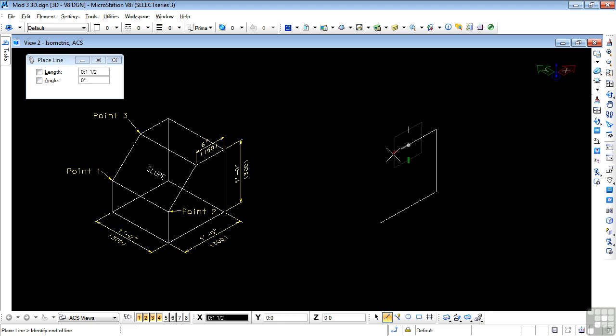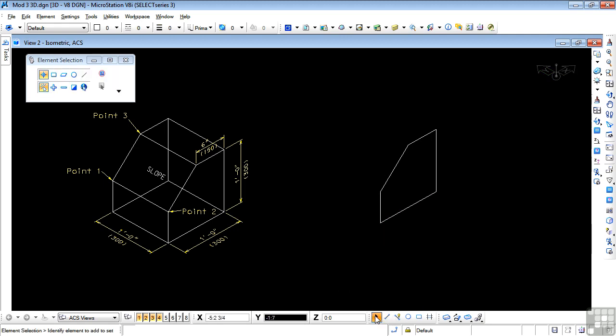Left click, drag down. Need to find the point now above the starting point here, 6 inches up. So I'll go down to here. AccuDraw is on, so I can press O to put the compass there, drag upwards by 6 inches, and again, find the previous distance marker, left click, and just drag straight down. And we're done. Now let's do this the easiest way.